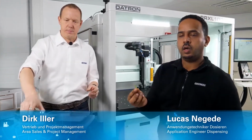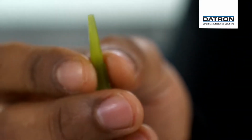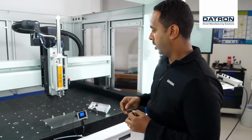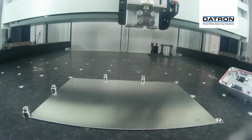Yes. So we have here standard needles on the market, which are plastic needles. This is the needle tip that we are using in our tools for dispensing the material. Now I will show you how we exchange this needle tip and measure it. This is a plastic needle, so it has a bigger tolerance. So we need to measure the length and the position of the needle in X and Y direction to have a good process in our application. So here we have a lock adapter.